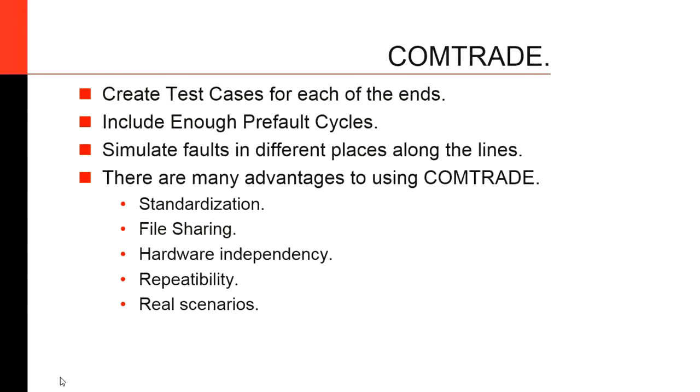And the other thing that it allows is not just to see, but to be played back using modern relay test sets. Since COMTRADE is standard, it also allows hardware independence in terms of testing.